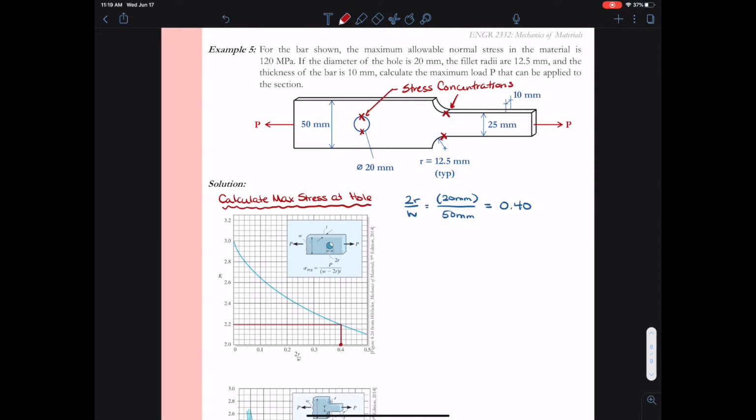It's important to recognize that we are obtaining this value for the stress concentration from a graph. So whenever we use a graphical method, there might be some wiggle room in terms of what the actual number is, depending upon how well you interpolate from the graph. But 2.18 should get us pretty close to the correct answer. Keep in mind that the curve that was used to generate this stress concentration factor, that blue curve, also probably has some variation from the test results.